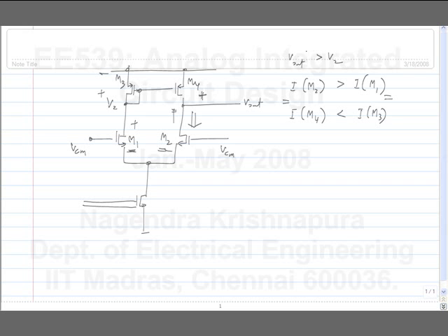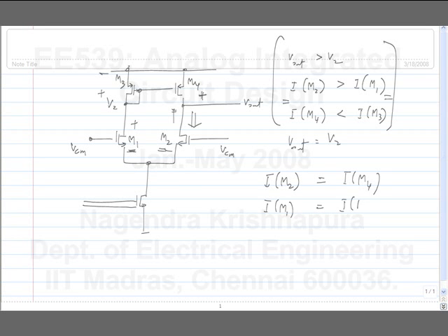Okay, so the only condition that gives you consistency is V out equals V2. Okay. Which one? No, it's not a question of stronger. This is exactly equal to this. That you agree? So similarly for the other one, the current in M1 and current in M3 are the same, right? So you can't have inconsistent conditions there. Okay.